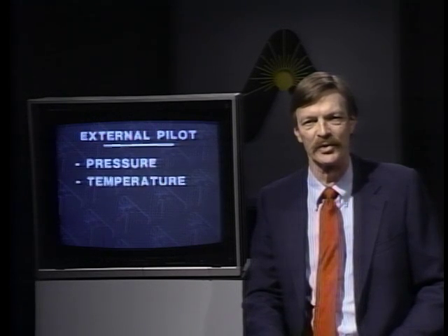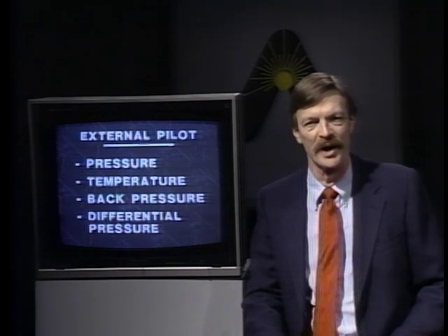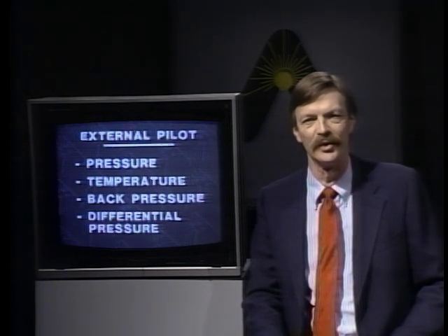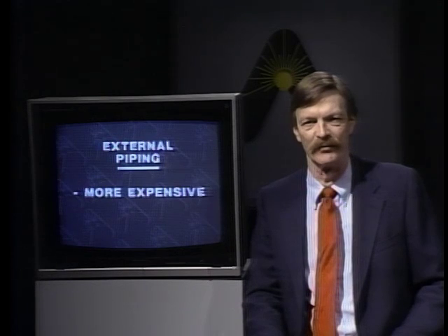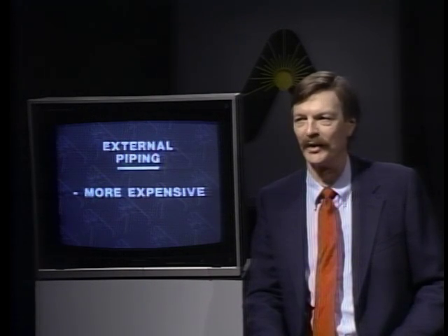External piloting permits the use of various types of pilot valves for pressure, temperature, back pressure, differential, or other control using the same main valve. Nonetheless, the installed cost is much more expensive than an internal pilot valve.